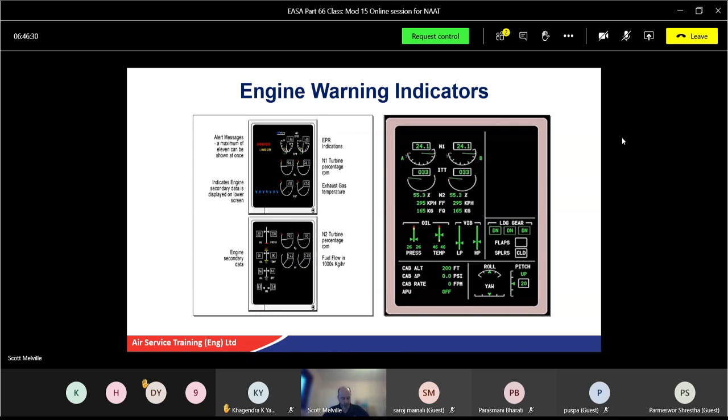What are normal thermocouples made from? Nickel chromium and nickel aluminium, so chromel and alumel. Chromel is your nickel chromium, and alumel is your nickel aluminium. Just as one you want marking in books as well, the chromel one is the positive wire and the alumel one is the negative wire. I meant to mention that before the break. So chromel is positive, alumel is negative.